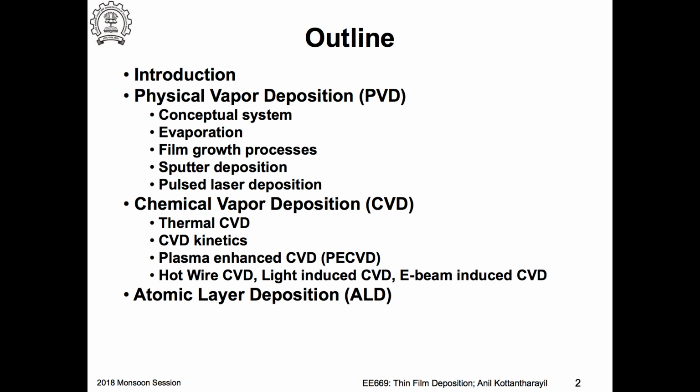And then atomic layer deposition is a very important process that was invented in the 1960s by a Russian scientist, but then it languished for a long time, and now it's becoming very, very important. So we'll see this process as well. Yeah. In fact, in the VLSI industry now, for gate stack deposition, people use atomic layer deposition tools, and we have again in the lab this ALD tool.